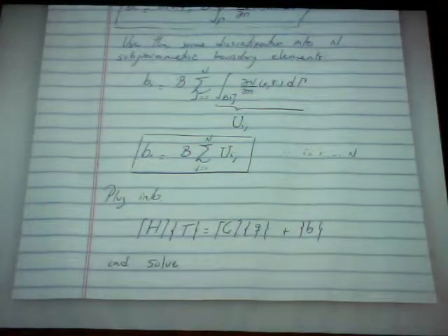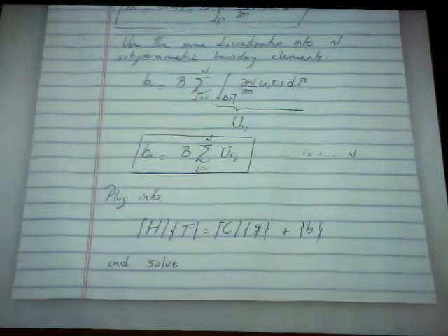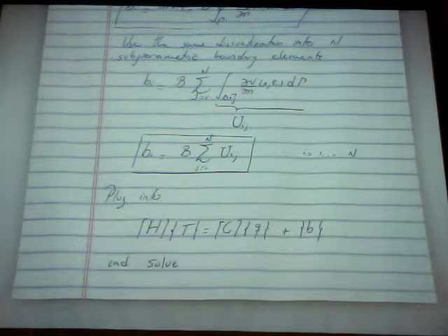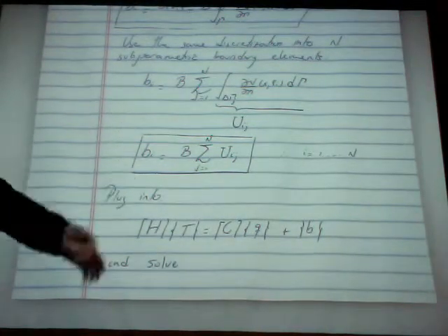And again, that's how we solve the other special case, which covers a wide gamut of cases, because more often than not, if there is a generation term, that generation term is going to be constant, like a distributed resistor over the domain that generates electricity, or some sort of chemical reaction that's taking place within the conducting domain that generates heat or energy. Okay, and in some very specific cases, the generation will be space dependent. But if the generation is constant, it is as easy as doing this, okay?